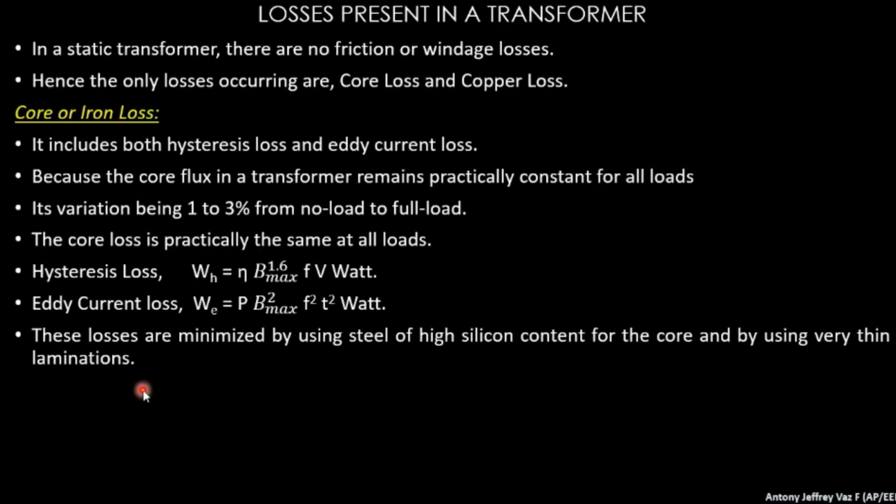Okay, now you can see what lamination is. Here the lamination is to avoid the eddy current. If a transformer is being loaded, the flux is going to pass through the core, and this flux is going to be alternating in nature. This flux will cut the transformer core.